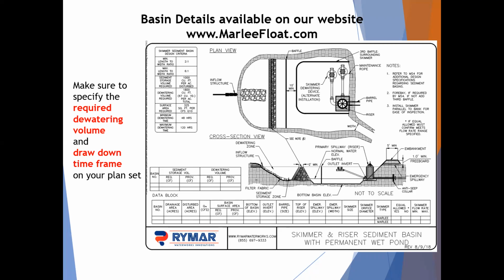So you may have say a 4-inch skimmer with, in ours, either a 2.5 or 3.5 inch orifice that you could add to it, and reduce it from 4 inches. Or like for the Faircloth, they have a plug and you can cut it down to within 1/10 of an inch, supposedly, to try to hit a more precise flow rate.